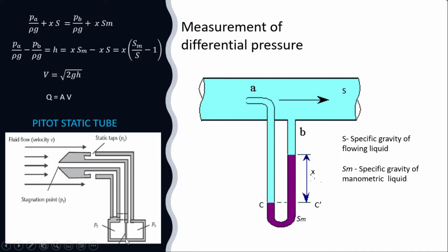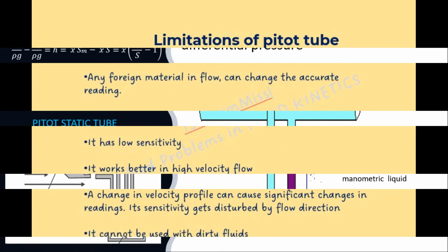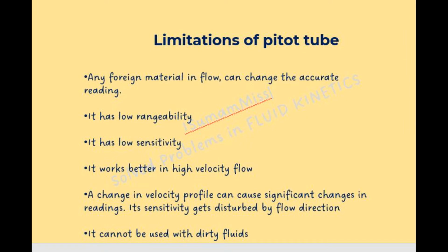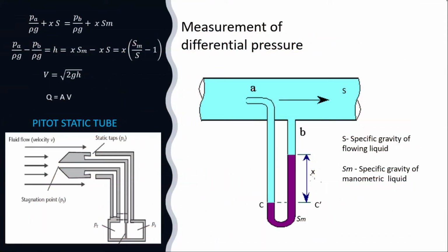And you can see a pressure transducer here. The pressure transducer which is connected here can be used to determine the difference between the static pressure and the impact pressure. So the Pitot tube can also be used to compute the discharge by measuring the velocity of the flowing fluid. So here also the only measurement you have to do in the field is the measurement of the differential pressure head. The solutions of the conceptual field problems are discussed in the next section.